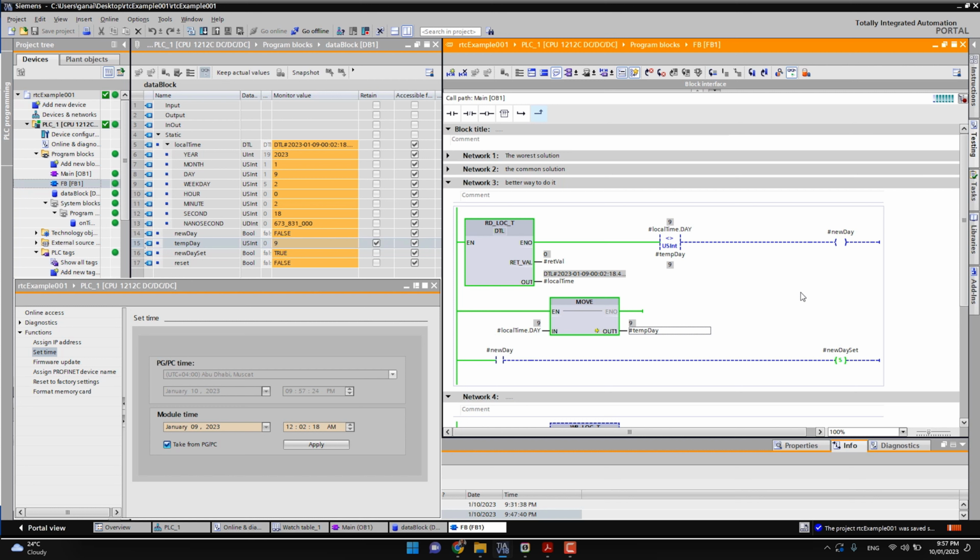So let us test this approach, and I just add a set here because the trigger will be for only one cycle. So as you see here, there is a simple set instruction, and I will trigger my reset. As you see here, I released the reset, and now we are waiting for the 10 seconds. As you see, we already have the trigger. And this is a very simple way to manage the triggers, and it will apply if you need a trigger daily or weekly or even monthly.